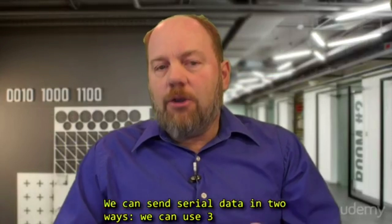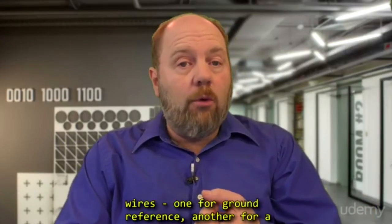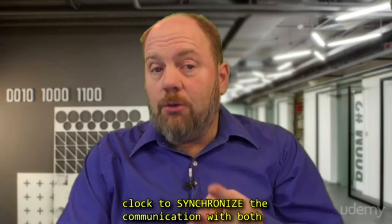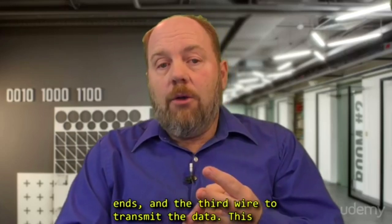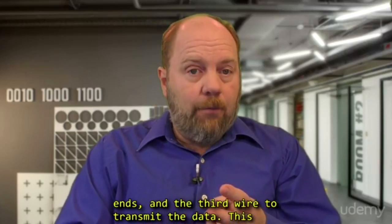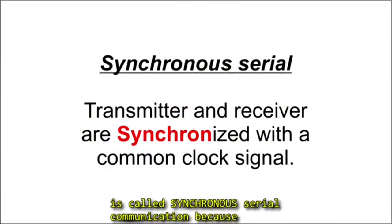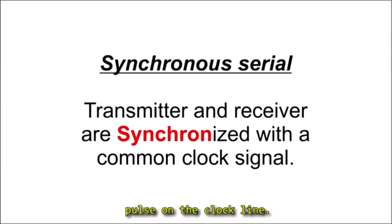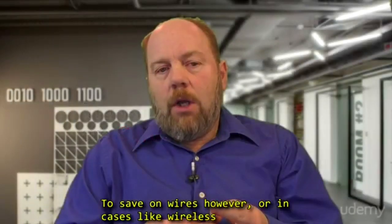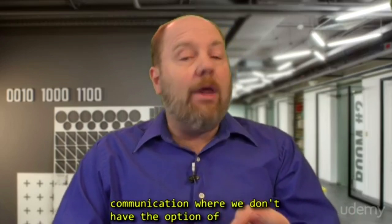We can send serial data in two ways. We can use three wires, one for ground reference, another for a clock to synchronize the communication with both ends, and the third wire to transmit the data. Now, this is called synchronous serial communication because the two ends are synchronized by that shared clock pulse on the clock line.